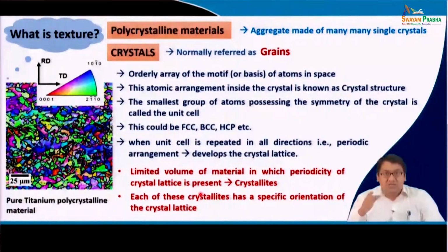So, what I am trying to say is that the periodic arrangement may not be maintained within a grain, but could be maintained in parts of the grain through some divisions which are boundaries, but not grain boundaries. They have misorientations which are lower than the grain boundaries and are known as geometrically necessary boundaries.